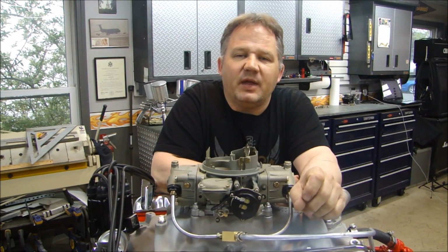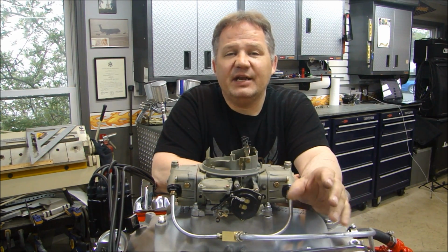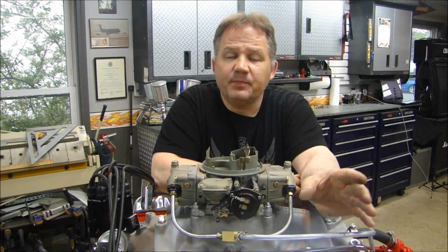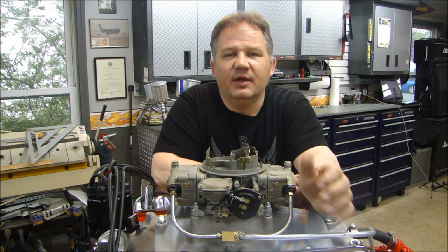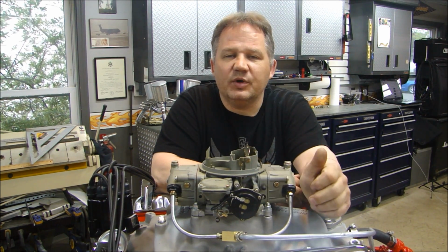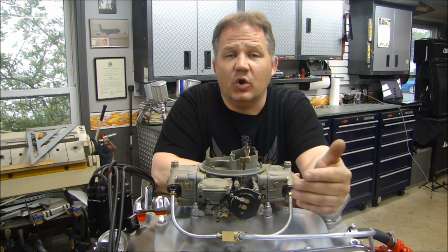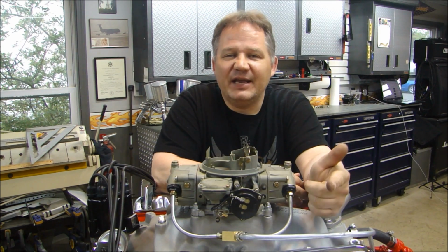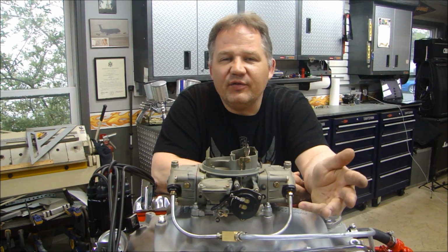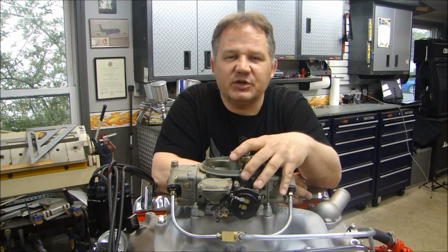So there you go, guys. I hope I've given you enough information to at least start picking a carburetor and deciding what's important when you want to choose a carburetor. Remember, if you're planning an engine, all the parts have to work together. The cam, the heads, the intake, the exhaust, it all has to work together, and the carburetor is an integral part of that. So maintaining vacuum, maintaining fuel velocity, maintaining the atomization of the fuel so you don't get dropout, delivering the fuel inside, the compression, and getting it out of the engine, it's all important. And it all starts with the carburetor.